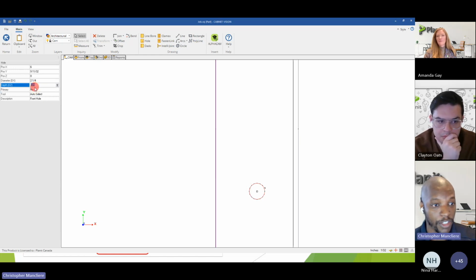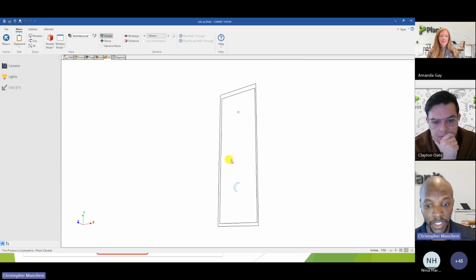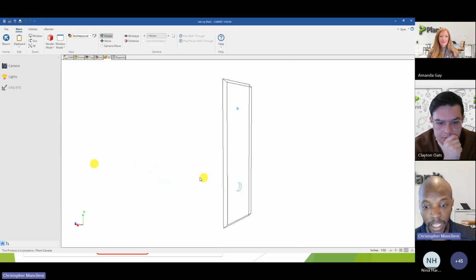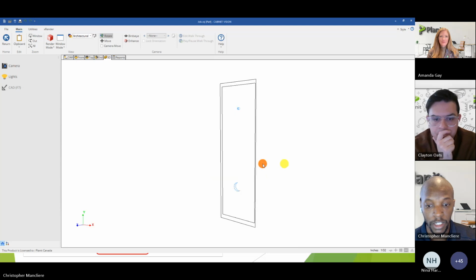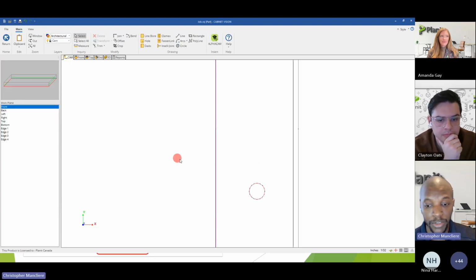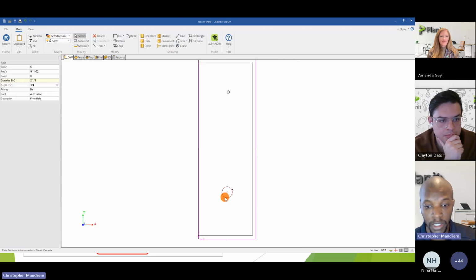So don't change it manually here. If you wanted to change the equation, just click on the equation symbol again to reopen it. So now if I go in my 3D, I can see that I have a through hole on my part. So now this through hole is done. I want it to be always centered on the width and the depth of the part. So I want to, for example, have this halfway through the width.